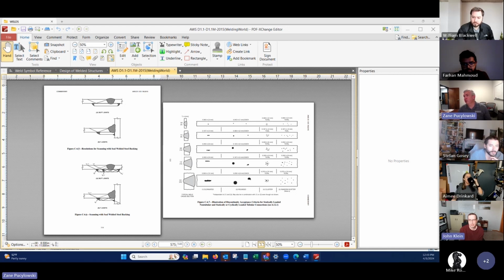Are there different calcs used for non-fillet welds? Is there a good reference for that? So you saw the little chart that showed effective throat. Shear is going to get to the effective throat in the same manner no matter what. So from us ME stress people, we now know how to handle that. For you guys, you probably got to find a different table, right? John may can answer that one better than me. Pros, cons of multipass. I mean, every time you start back over, you can add a flaw or an inclusion to the weld that can decrease its strength.